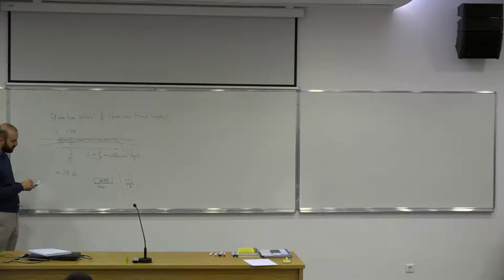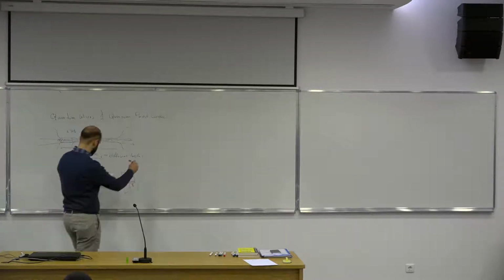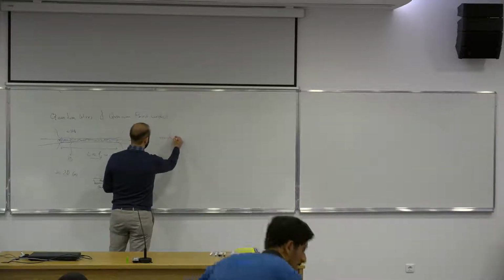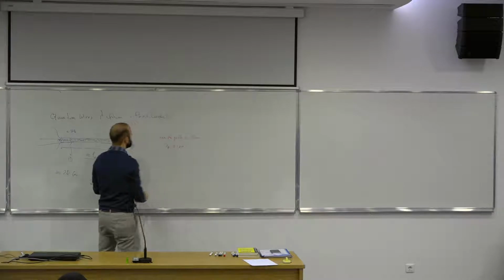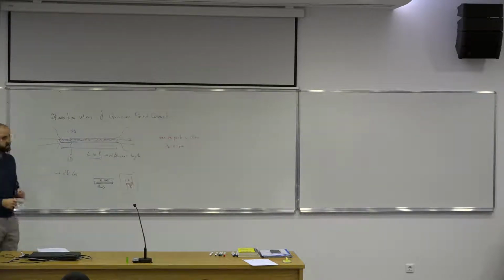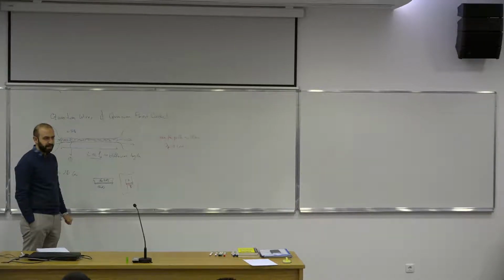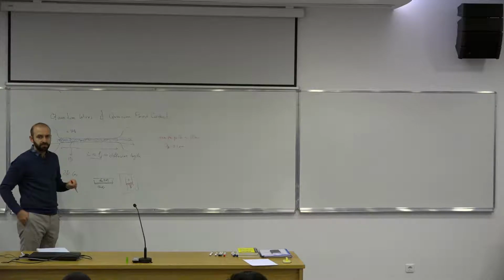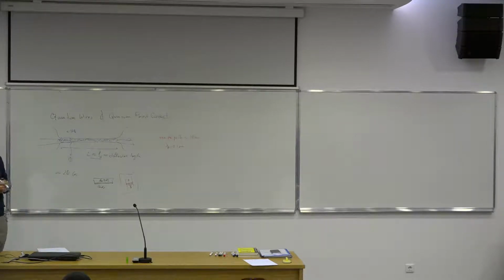As I mentioned in the previous lecture, for the case of metallic wires, they're always going to be diffusive unless you make them extremely short, because for the metallic wires, typically the mean free path is about 10 nanometers, and the Fermi wavelength is about 0.1 nanometers. So whenever you have a metallic nanowire, it's typically a diffusive wire. But in the case of semiconducting wires, I think you can do similar experiments with silicon at very low temperatures, but there aren't actually many examples that you can find like really standalone nanowire. Carbon nanotubes is another example, but in the case of carbon nanotubes, it turns out that making good contacts is very difficult.